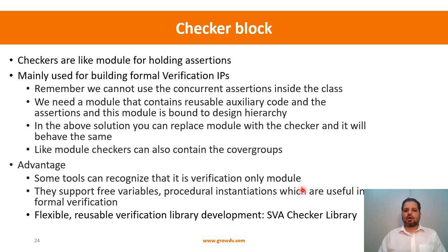There are also some additional features available, called free variables and procedural instantiations, which are more useful for formal verification. So a checker is a container, and as I told, it's more useful if you are building formal verification IPs. It's a flexible, reusable verification library development component, and it's used in the SVA checker library, which you can Google and find out more about.